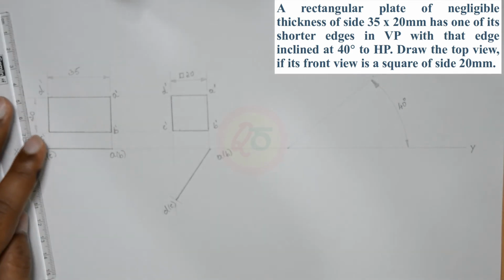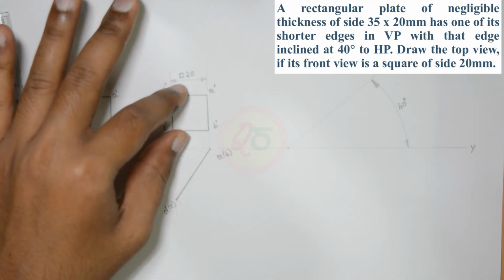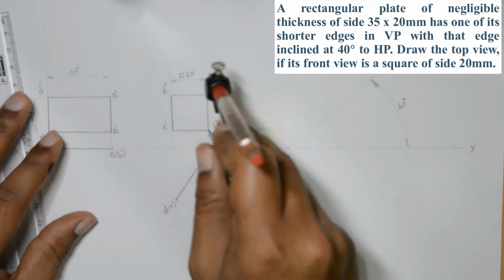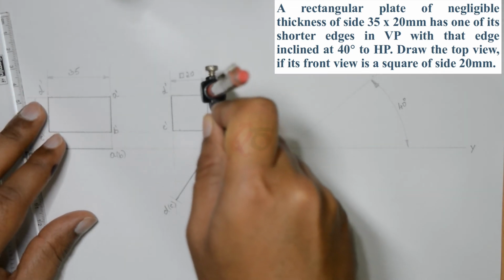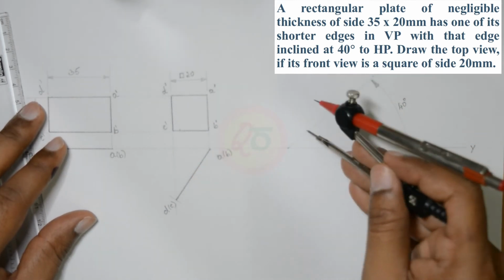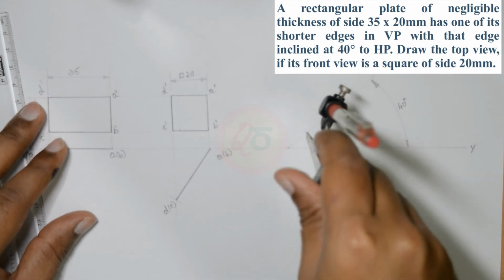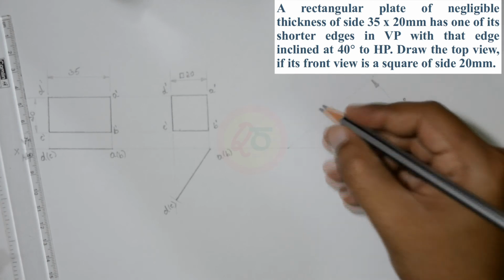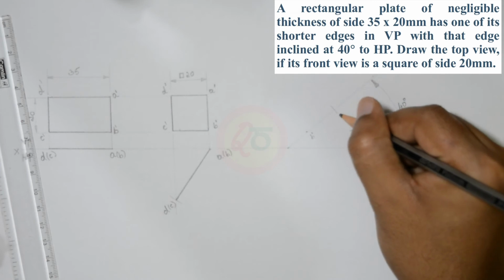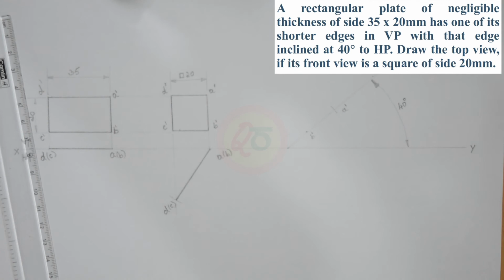Now you need to rotate the front view of the second position on this 40 degree line. The dimensions remain the same. So I'll measure B dash to A dash, select a random point away, cut an arc so that the needle end will be B dash, and the upper end, where the arc intersects with the 40 degree line, will be A dash.